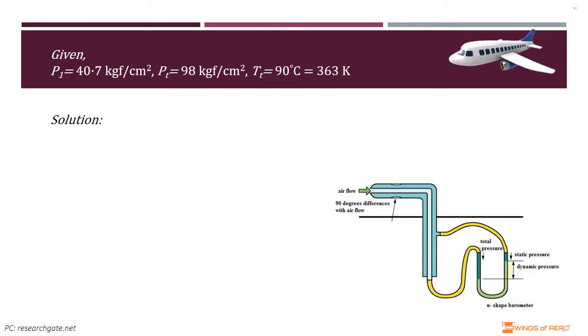A Pitot tube is a flow measurement device used to measure fluid flow velocity. By definition, the change in density of an incompressible fluid is zero. This means an infinite velocity of sound. However, real fluids are not truly constant density fluids and always have a finite acoustic velocity.